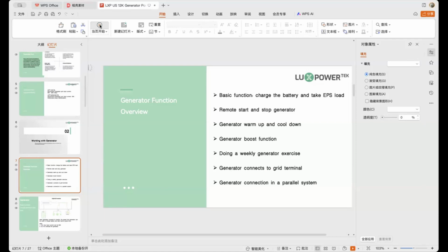You can set control here. You can set control of the discharge according to the voltage or to the SOC. For example, here you choose SOC, you can see the SOC is green, and you set 20% off-grid cutoff SOC. Then if the SOC is lower than 20%, the generator will be started. And also in some applications, the SOC may still be high, but sometimes you know that the SOC is not accurate actually from the BMS.